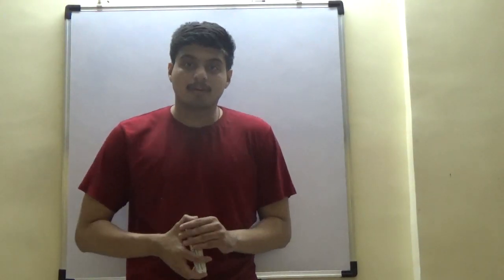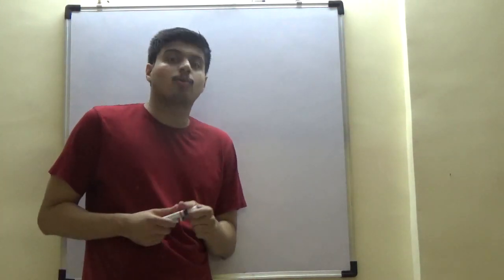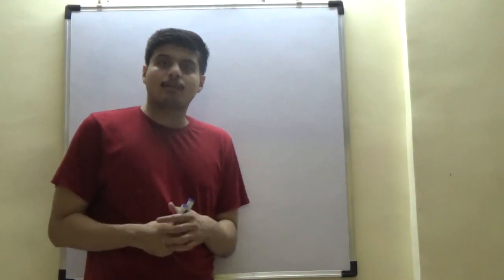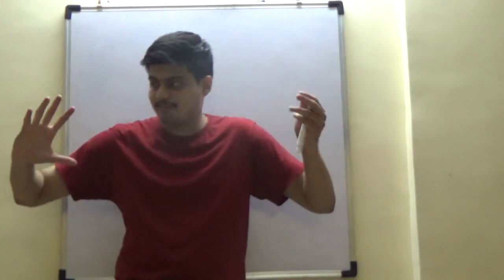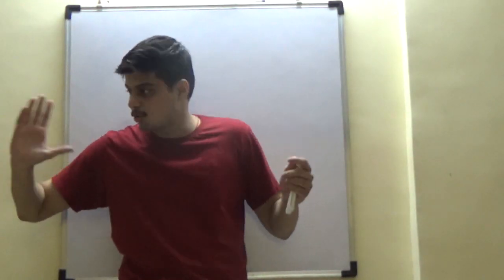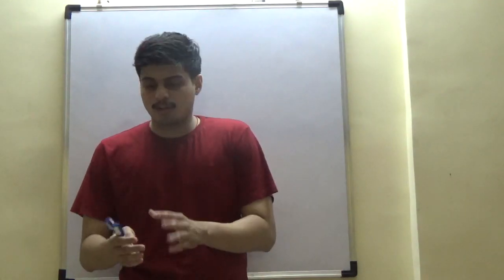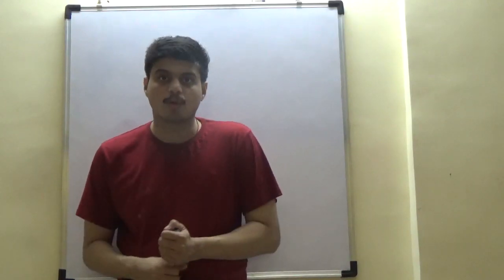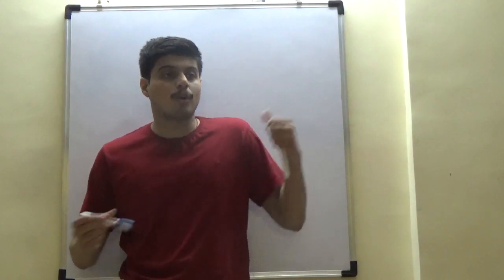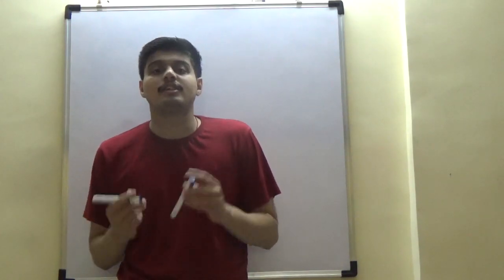Welcome to this tutorial 2.2, which is about understanding more practical applications of the torsion theory that we looked at. We have already practiced a set of 2-3 problems as we discussed these mathematical foundations and the physics framework of the problem, as we looked at stress functions, the Prandtl function. In this tutorial we are going to now summarize everything about the torsion, not of course the Airy stress function tutorial which we already have, but more about these warping functions, solving a few sections, understanding this torsional rigidity J